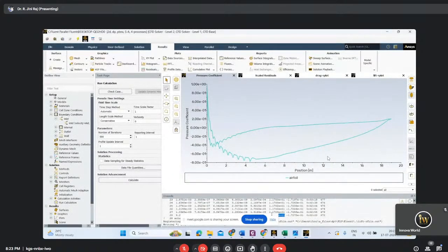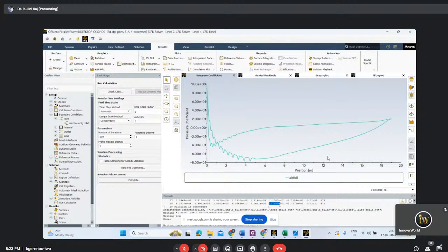Not wrong, but the values are not what was selected, as per the boundary condition you have given, 0.17. The velocity is also very low. Yes, velocity is low, but the CL value we will get is whatever we are giving. Whatever is prescribed will come that way only. This we need to correct. It will be like 0.117 for zero angle of attack for this particular airfoil. So we have to correct it. Other things are all correct.